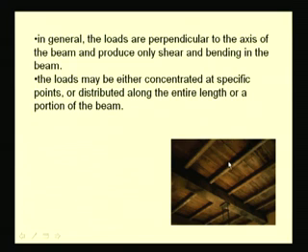The loads could be either concentrated, as you see for this big beam, where the slender beams apply the load at these points, or it could be a distributed load like you see for these slender beams, where the roof planks apply continuous loading all along the member.